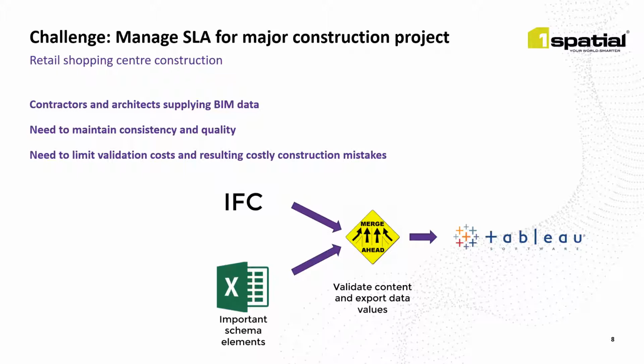Using FME, we automatically consumed the BIM IFC files, allowing us to expose the hierarchy of building information stored in the files. The customer stored the key parts of their BIM schema in an external Excel resource file, as this allowed them to easily amend it to support the project. The contractor's file was then automatically assessed against the allowable rules, and an enhanced summary was produced that could be connected into a pre-configured Tableau dashboard.